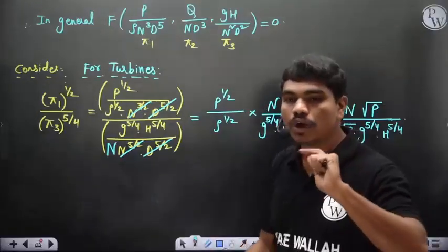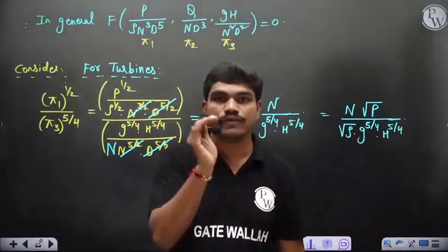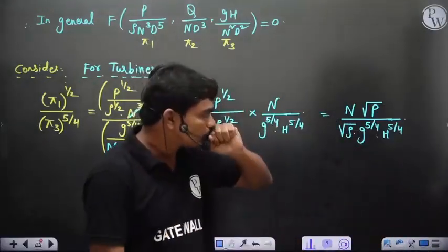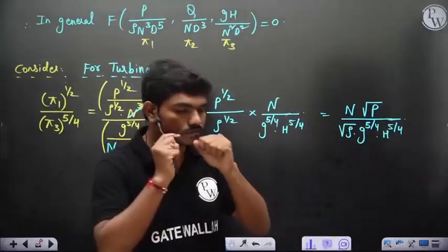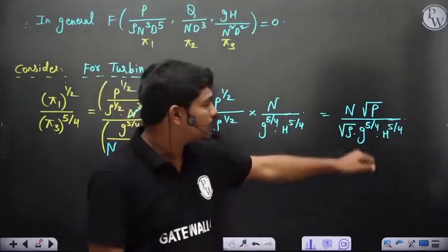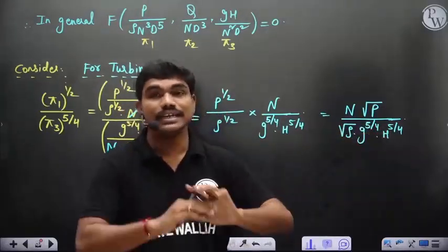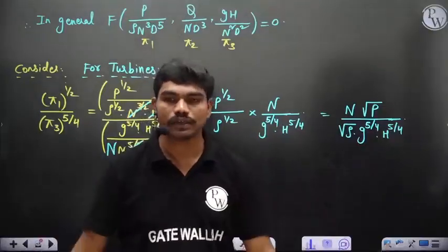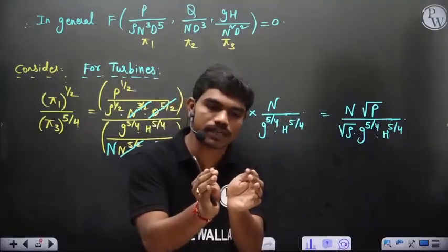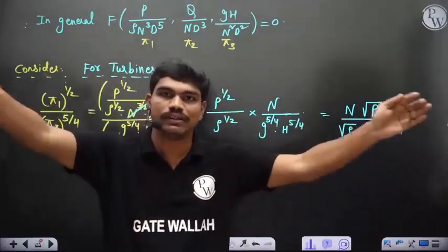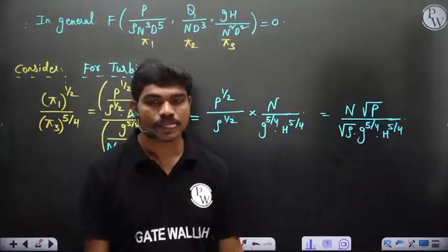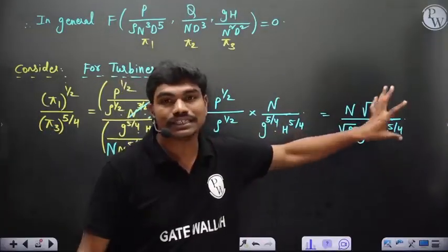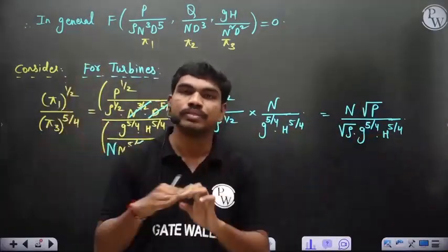So it tells you of a particular dimensionless number where there is a scaling of power and head simultaneously, irrespective of the size of the diameter. So you can conduct the experiment on this much diameter wheel or this much diameter wheel or a very big diameter wheel also, doesn't matter, as long as this dimensionless number is made equal between the model and the prototype, results match.